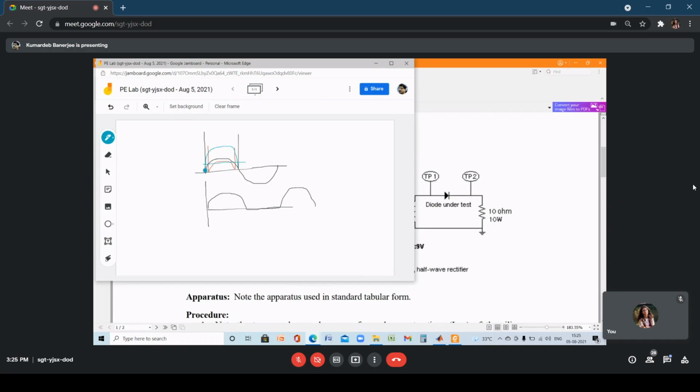Okay, so when we have a 2 volt supply, 0.7 volt occurs at this particular time instant. Now if I increase the amplitude, it will definitely occur before this particular time. That means the conduction angle will improve if you increase the amplitude of the secondary waveform. So that's basically an observation.